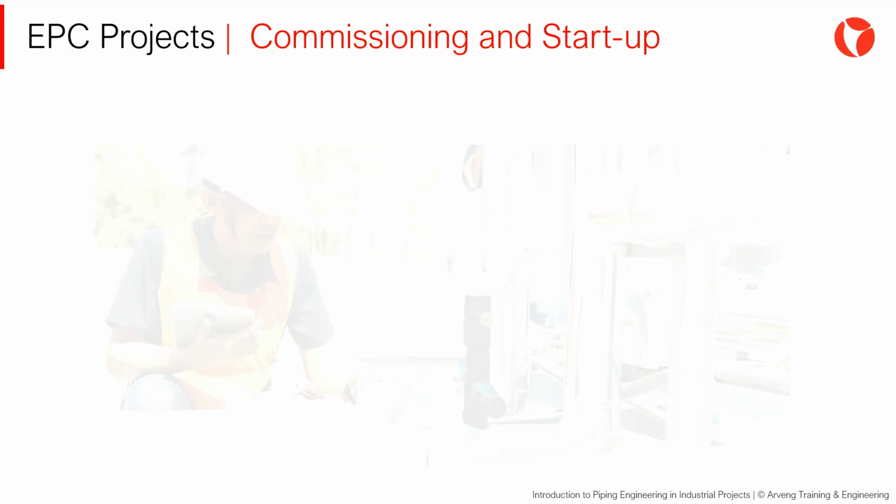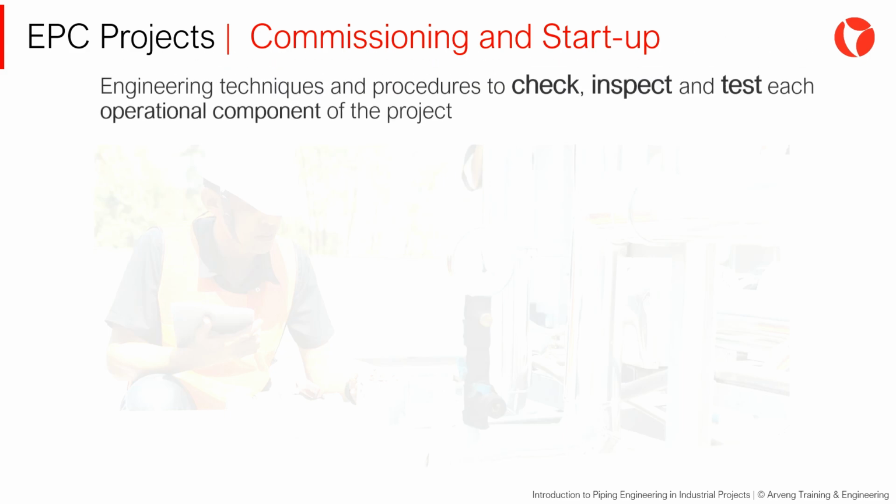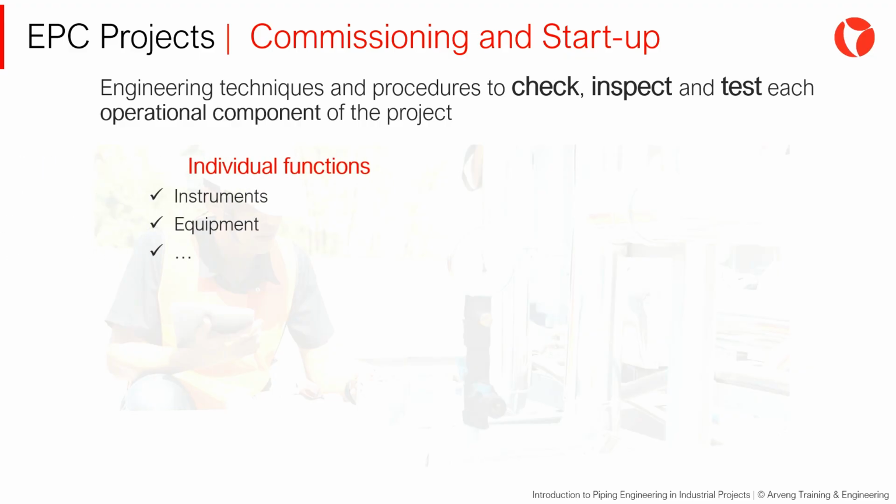Once construction is complete, the next steps are commissioning and startup. Commissioning involves the application of engineering techniques and procedures to inspect and test each operational component of the project, from individual functions such as instruments and equipment, to complex equipment such as modules, subsystems, and systems. The main objective of commissioning is to ensure the safe and orderly delivery of the unit, guaranteeing its operability in terms of performance, reliability, safety, and information traceability.